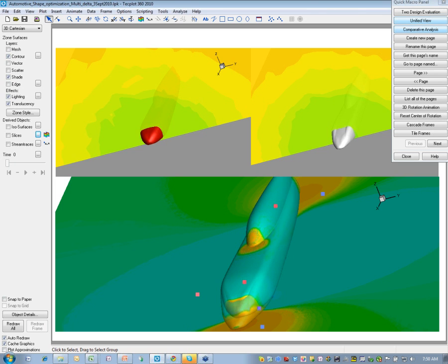There's another question about how did you do the comparison and were the grids the same? In fact, in this model, the grid points were the same. The models are morphed, but point by point, the values were the same. If you don't have that registration, what you typically do is create a mesh that you can use for interpolation, and then that interpolated mesh will be used for comparison.